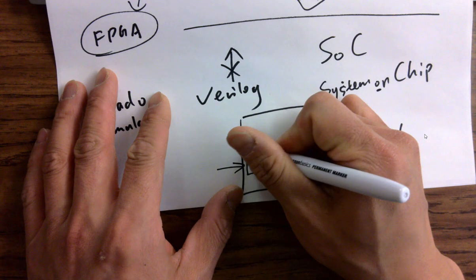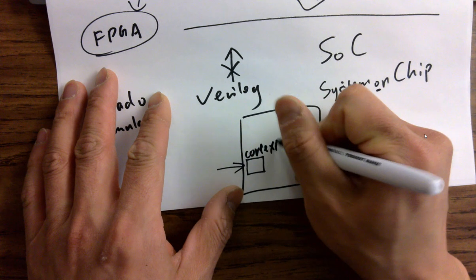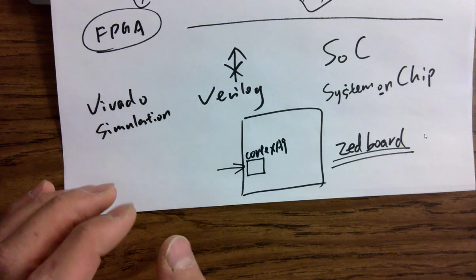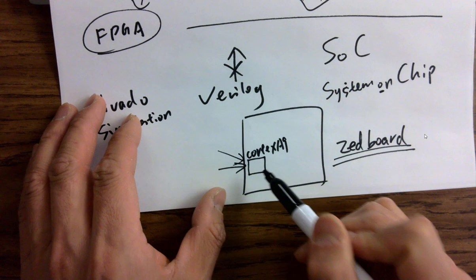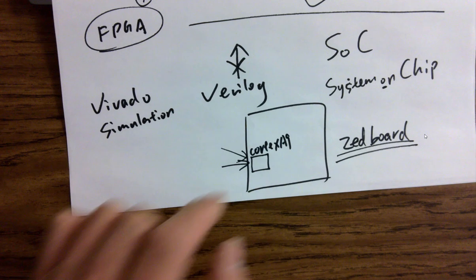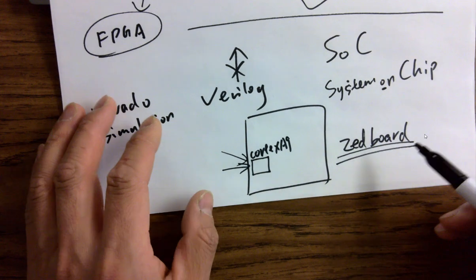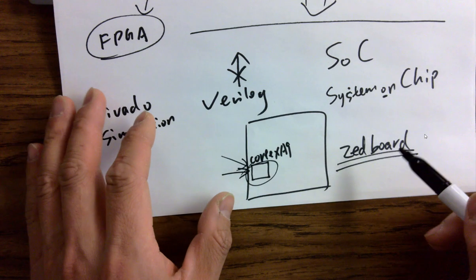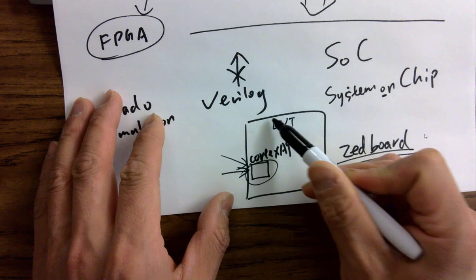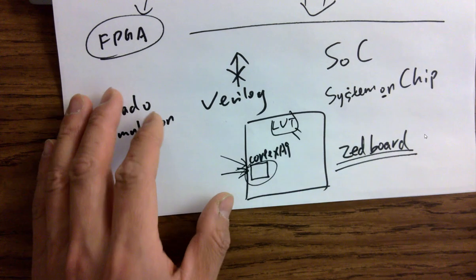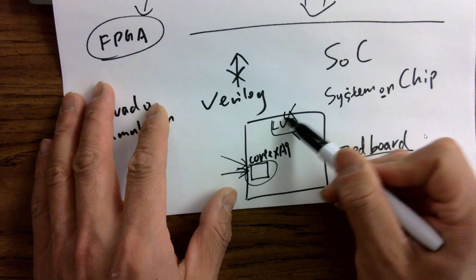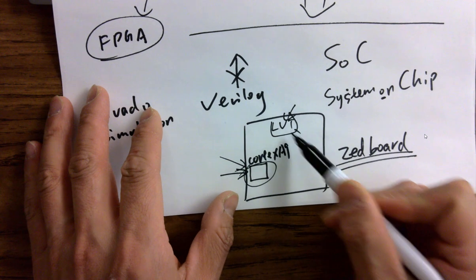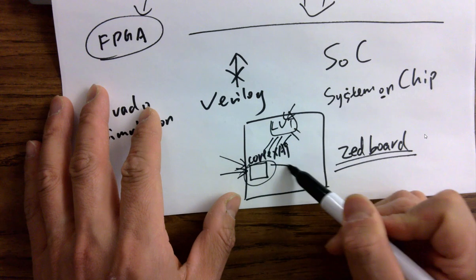This is a Cortex A9, I remember. It's from ARM. That's why the Zboard is more expensive, because they have to purchase the ARM core as IP and place it into the FPGA chip. They're selling the FPGA chip with some hard cores already physically implemented into the FPGA, with all the LUT units and interconnections as well. So you are able to design and customize the digital circuits in here and make interconnections with the hard core as well.